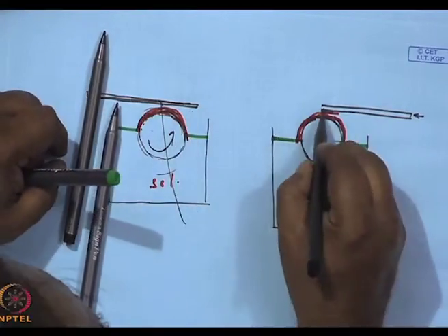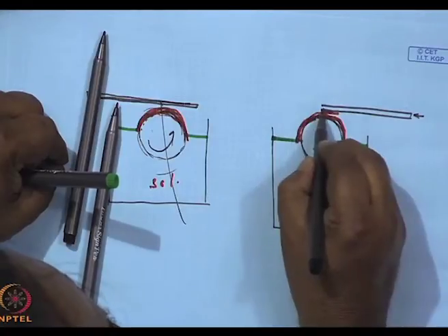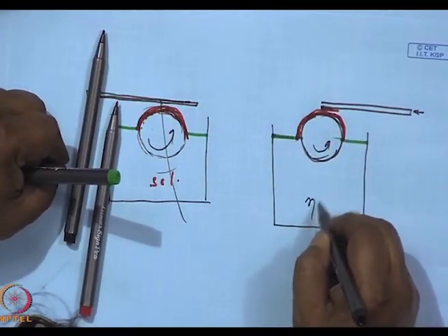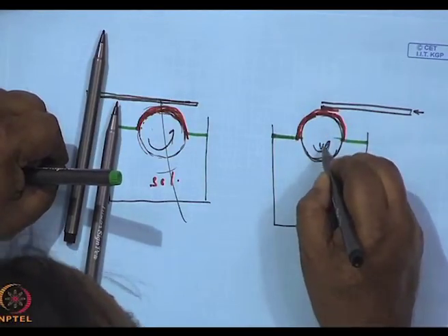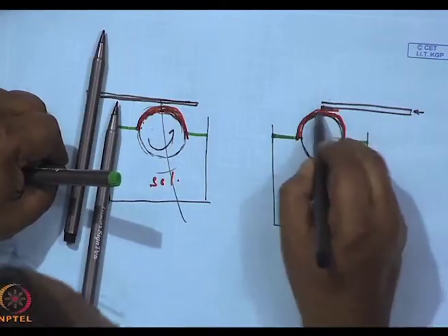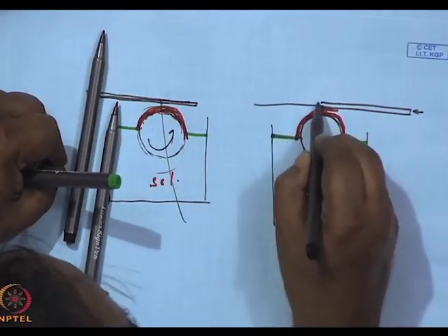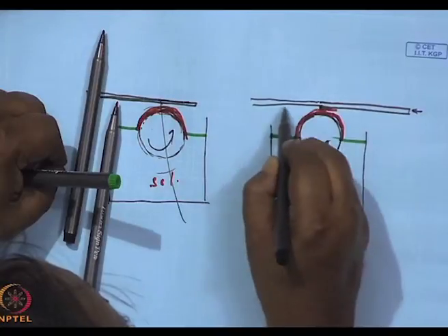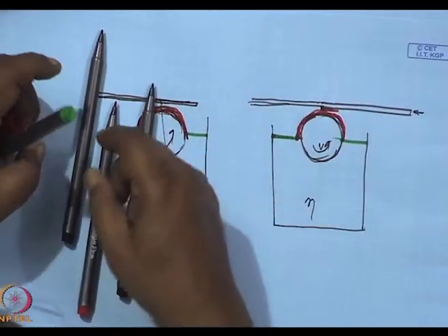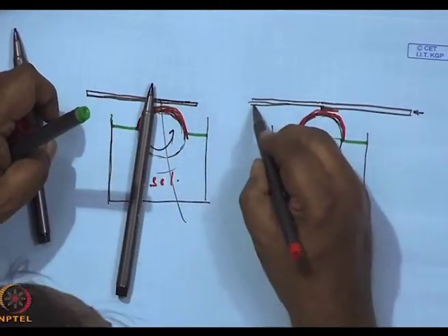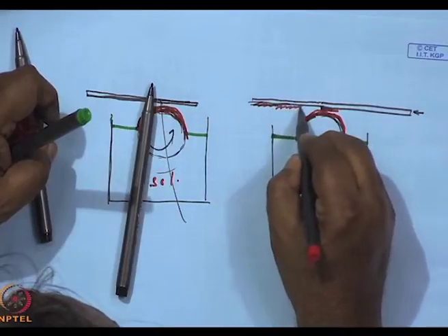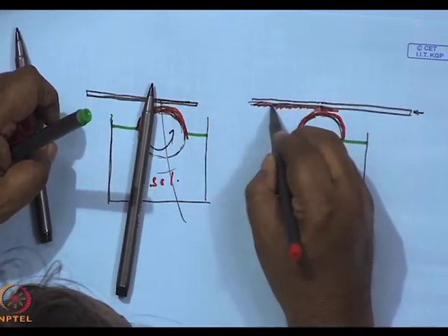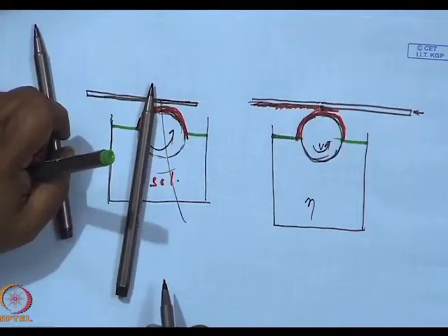And if I move this slow enough, control the viscosity, control the rotational velocity, and I can keep pushing this substrate, what I would be getting is a very uniform coating of the liquid on the substrate surface.